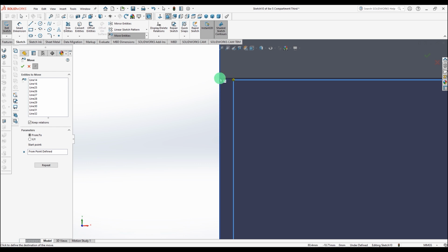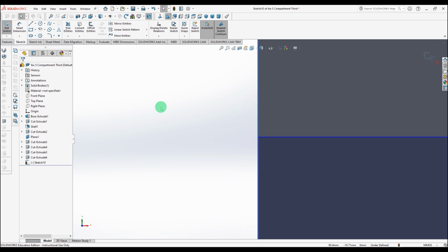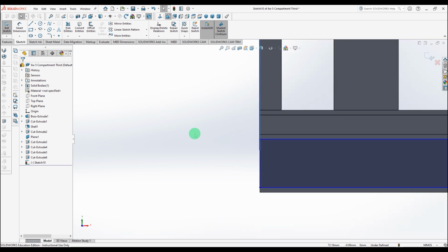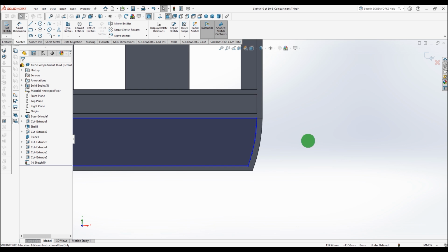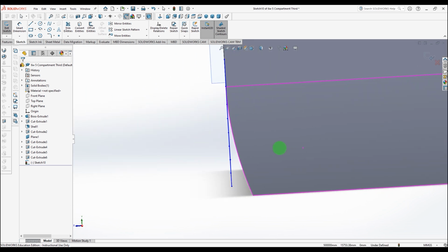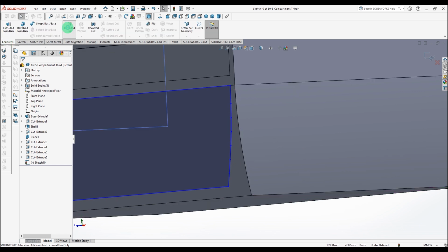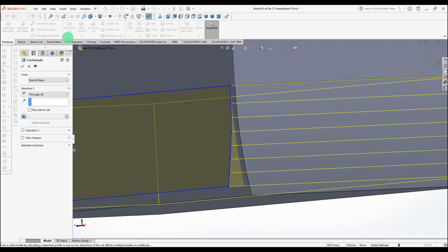So with this profile, again I'm going to do an extruded cut, and when that removes the material it'll leave the beading around the edge of that tumble home panel. But it's slightly more complex here because that tumble home or turn under is a curved section. So when I come to my extruded cut tool, I'm going to set it to be offset from that curved surface.